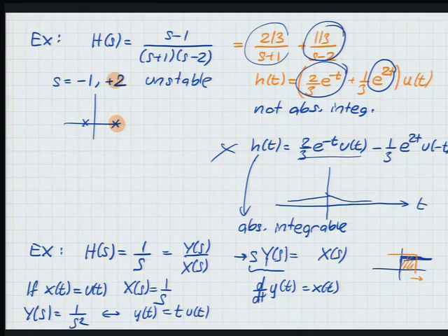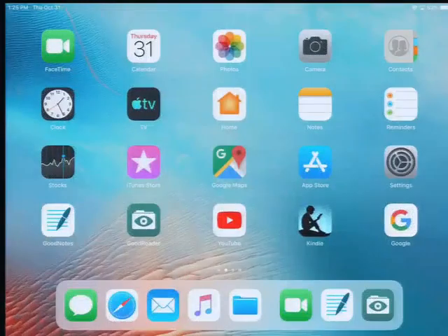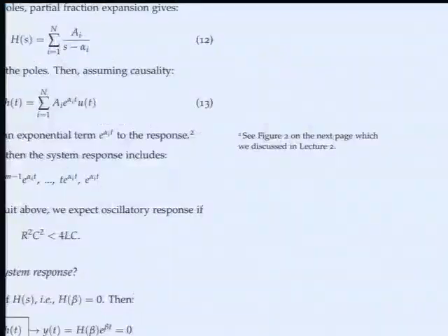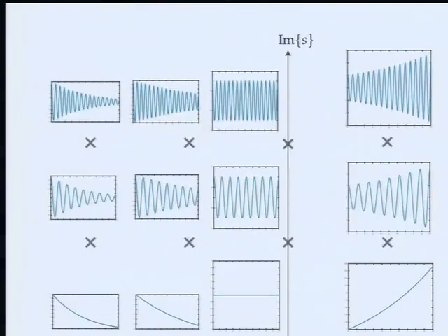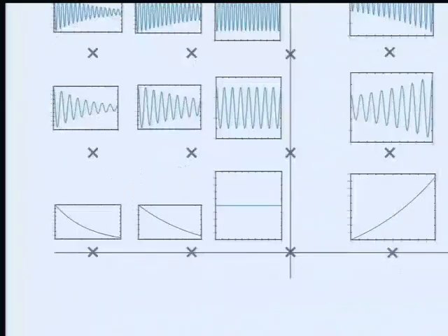So the essence of this argument here is that, again, going to my picture, to create instability, to create instability, you have to hit this system with an input that matches the pole on the imaginary axis. If the pole is at 0, you have to hit it with a constant input. Then you take the convolution of a constant input with a constant input, and it blows up, right?